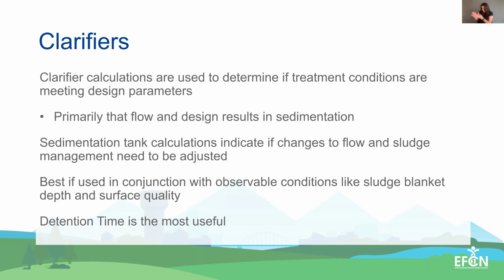Our sedimentation tank calculations indicate if changes to flow and sludge management are needed. And then these calculations are also best used in conjunction with some of our observable conditions, like a sludge blanket, specifically the depth of that sludge blanket and the surface quality. So this can help us understand if we need to make some adjustments.